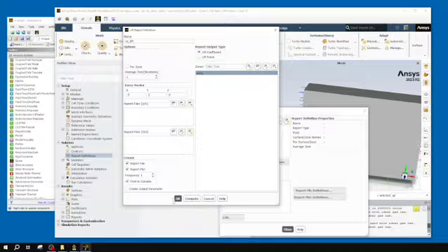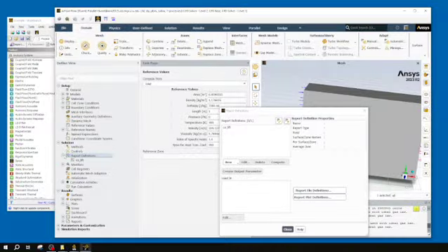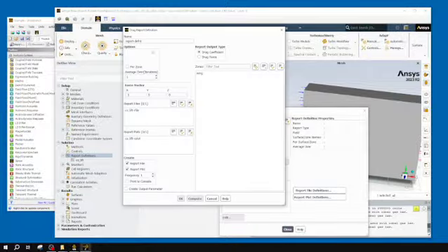And we can see if I press that plus, we get a coefficient of lift. Since it's still open, I'm going to do another new force report. This time I'm going for drag. I'm going to call this co_drag. Drag coefficient, now it's in that X direction. I'm going to give it a print to console, want a report plot, report file, that all looks good.